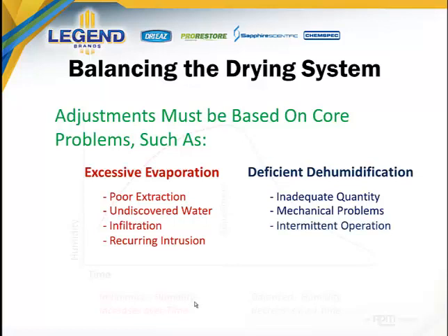Third, look at the dehumidifier's hour meter. Has the dehumidifier been operating consistently throughout the entire period after it was installed? Very commonly, the reason for an unexpected high humidity in a space is because the dehumidifier has only been operating intermittently. This may be because occupants have been turning off the equipment for periods of time. If this is the cause, then unfortunately, adding another dehumidifier to the project is simply going to give the occupant another power button to push when you're not there.